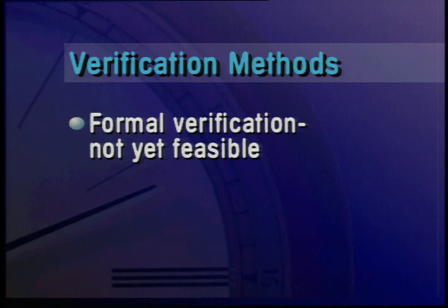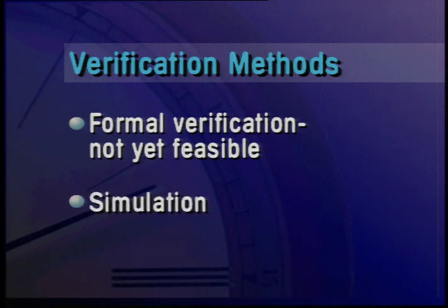Now, there's no real methodological requirement as to how the verification is done. There are basically two choices: formal verification and simulation. Ultimately, formal verification is the most attractive solution. That is, an analytical method which looks at the design and the specification in some way and determines if you got the design right. However, to date, this technology is not even close to being industrial strength, and as designs get more complex, the problem is not getting any more solvable. What that leaves us with is simulation.